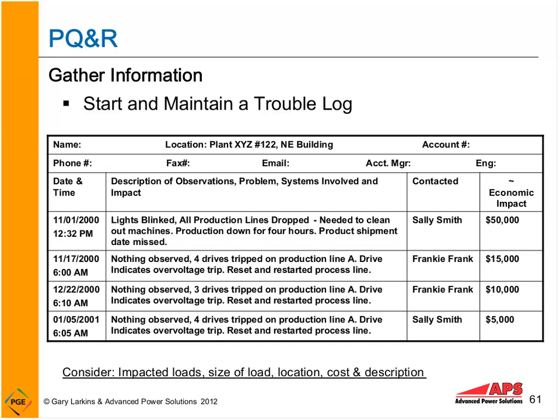If you're having a problem or your customer is having a problem or client, what time is the system going down? Maybe it's the startup of their chiller in their facility that's causing the issue. And maybe they start their chiller every morning at 7 a.m. So those are things, by documenting the power quality anomalies, we can help to become a sleuth in this whole process and document what's going on in the system.